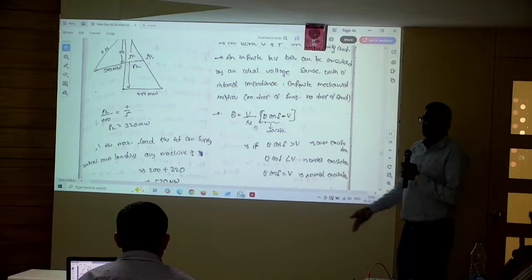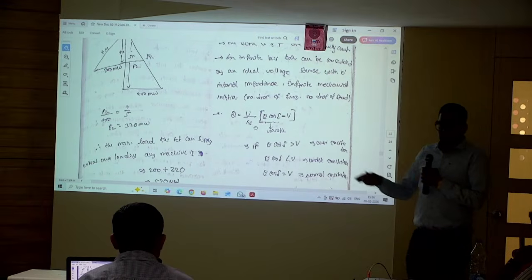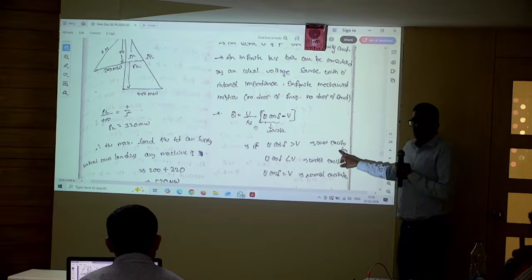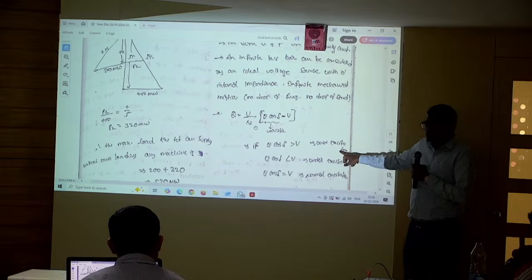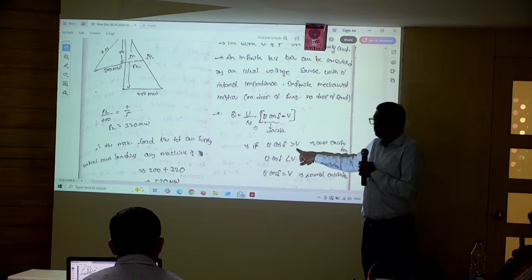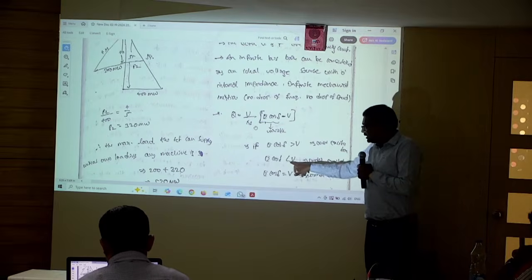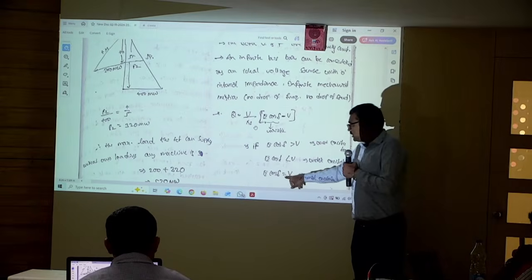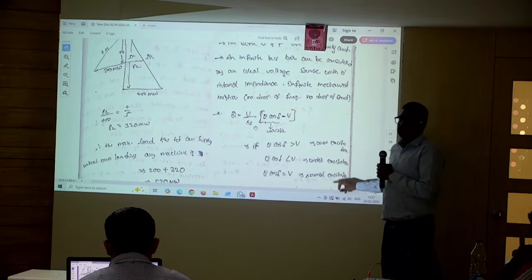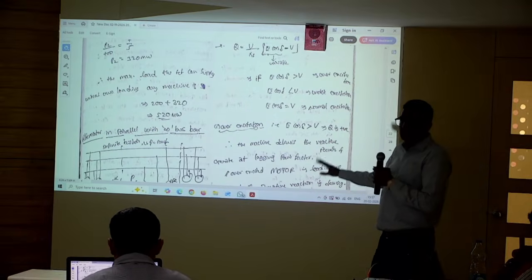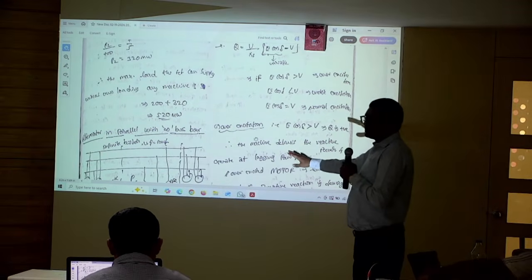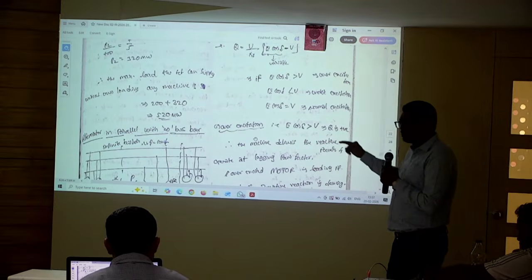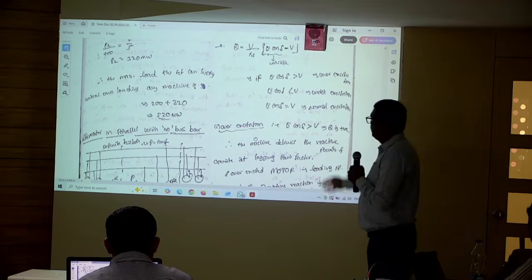So if this is increasing, how can it increase? EMF. How can we get increased excitation? If the machine is subjected to over excitation, E cos delta will be greater than V. If E cos delta is less than V, it is subjected to under excitation. If E cos delta is equal to V, normal excitation. These three cases we are going to see now. After that, we will see the analysis of how the reactive power transfer happens when it is connected to the infinite bus bar.